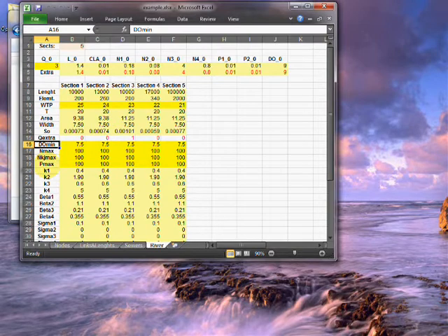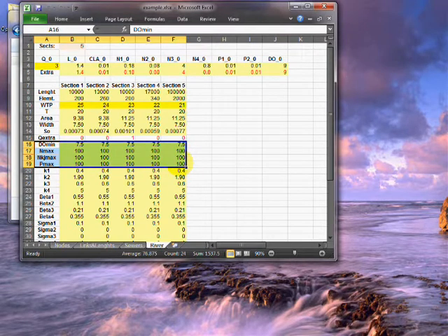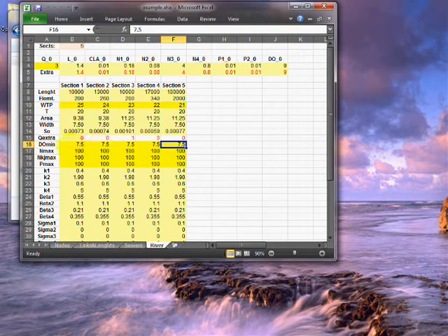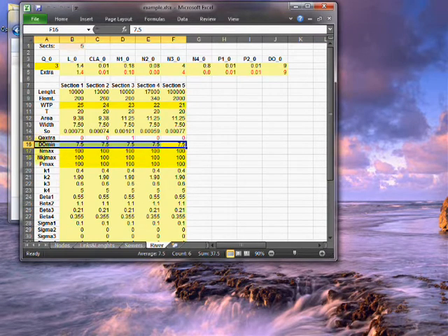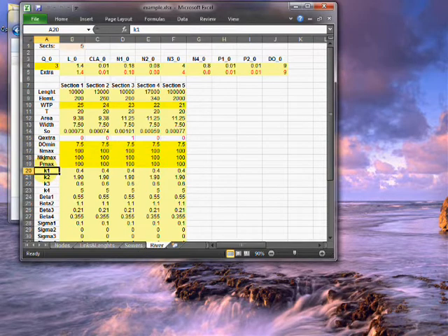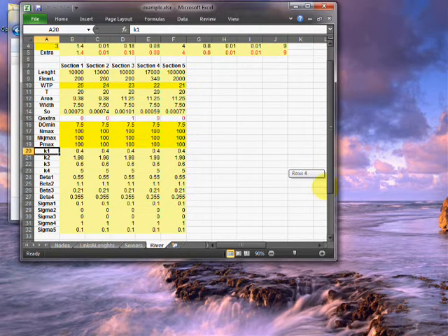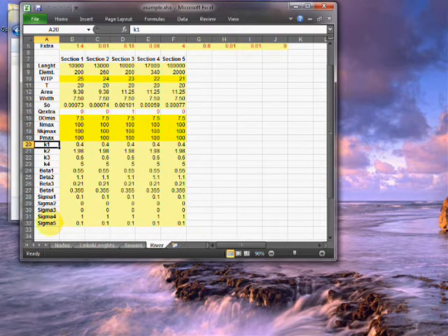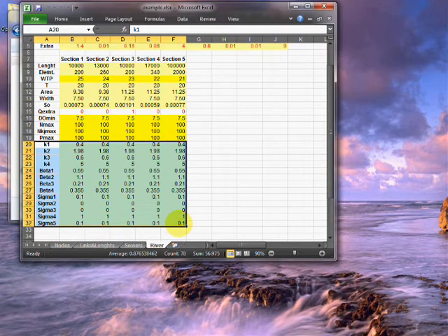The subsequent 4 rows define the minimum or maximum values for the water quality indicators. These values are defined by the user to represent the water quality constraints of the problem. In this example, the water quality of the river is defined in terms of dissolved oxygen. Its minimum value is constrained to be larger than 7.5 milligrams per liter. This is required in all the 5 reaches of the river. The remaining rows define secondary parameters. All this information is required for the water quality simulation model that is incorporated in the program.